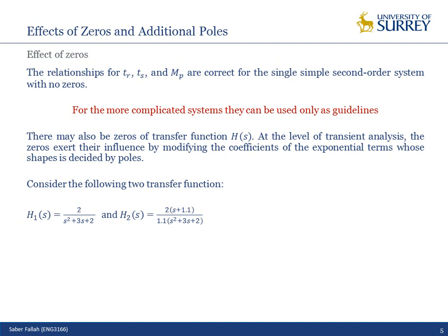How can we calculate the DC gain of the system? When we put s equal to 0. Yes. If I put s equal to 0, here the DC gain will be 1. 2 will be cancelled with 2, so it will be 1. So this is just for normalizing the transfer function; it won't affect anything of the response. To make sure that we have the same DC gain, I put the 1.1 in the second transfer function. Okay. If I want to check the step response of the system, I need to first find the poles and